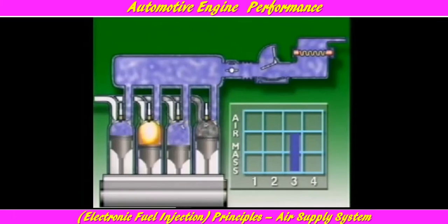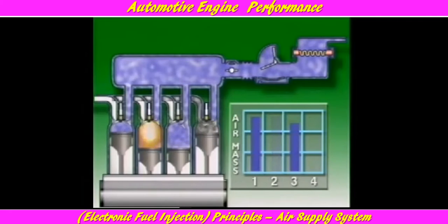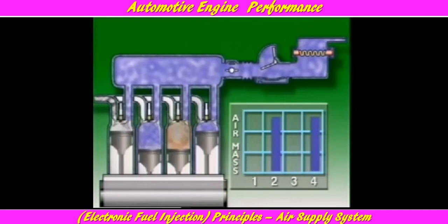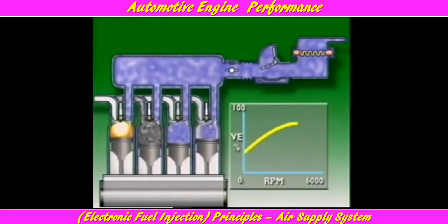The design of the intake system determines how large an air mass can be drawn into a cylinder at any given engine RPM. This is where most advantage can be taken of electronic fuel injection, since it can achieve exactly uniform distribution of the air delivered to the cylinders. With unobstructed passages to each cylinder, the cylinder fills with air as efficiently as possible. The breathing of the engine, or its volumetric efficiency, is improved.